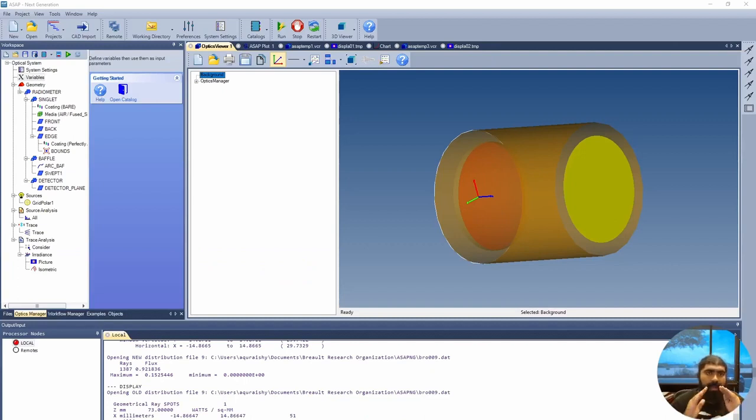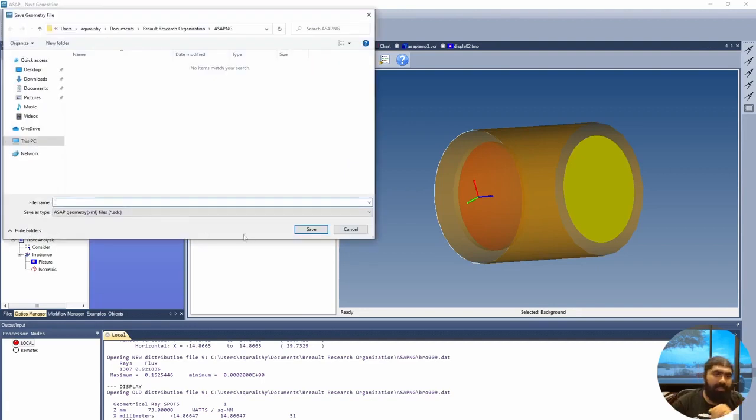Hey, Amr here. A really quick note that I forgot to add in my initial recording is you'll see this workspace right here. One of the really important nuances on this is where you save your system, because it's not by going to File, Save. You'll notice here that there's no save options here. They're not available. If you want to save your optical geometry build, you have to go here and press the save button in the workspace. My apologies for not hitting this earlier, and hopefully this quick interlude will help you guys later.